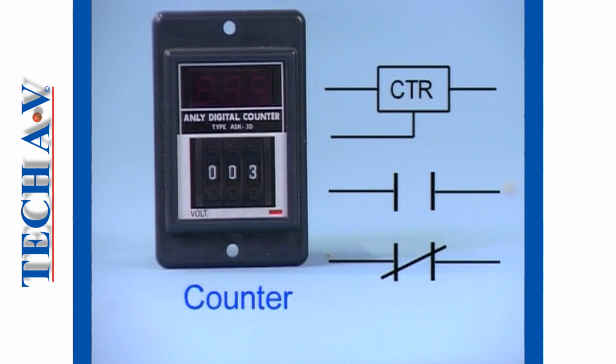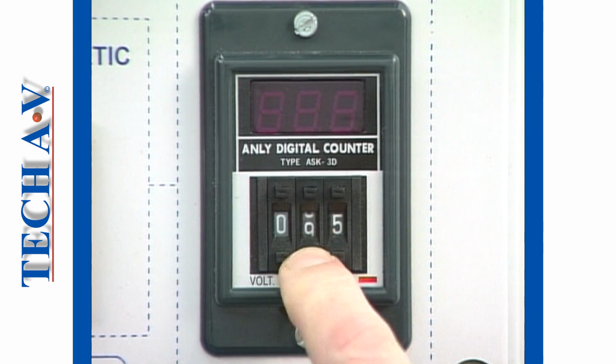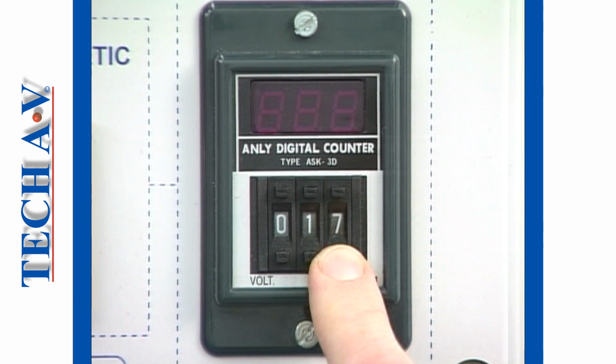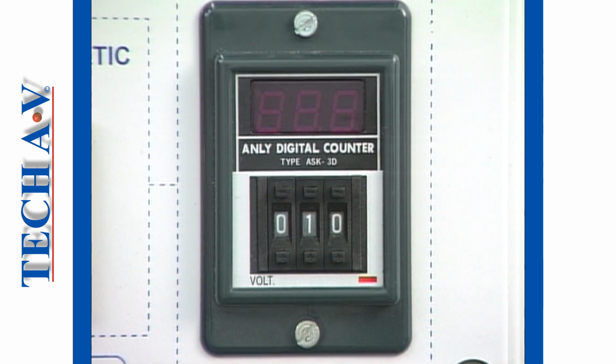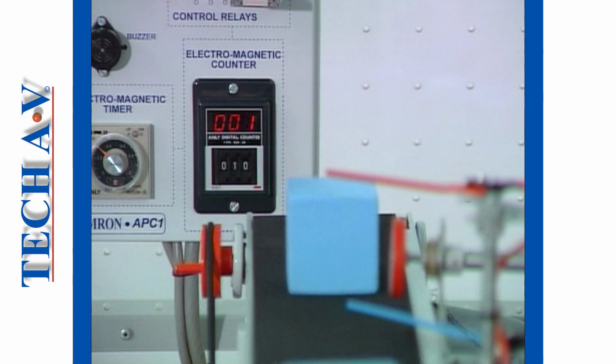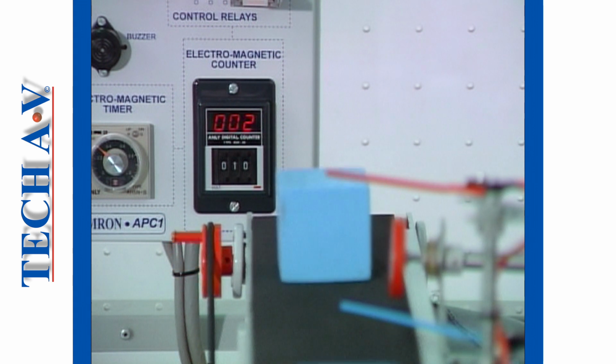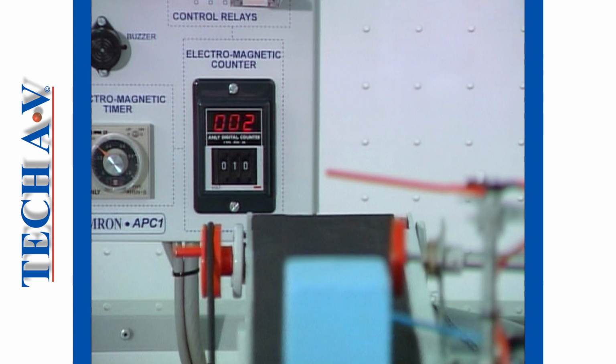The final device in the logic group is the electromechanical or electronic counter, which is used to count system events. For example, we preset the counter to 10 on our block sorting machine using the thumb wheel input switches. And whenever a short block passes the limit switch, a voltage signal is sent to the counter's input circuit and the count advances by 1.